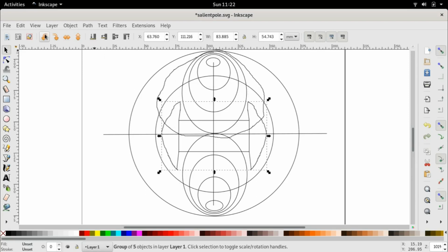In comparison, if this rotor were to be rotated by 90 degrees, we see that it's totally different. Now in this case, since the rotor position is in the horizontal direction, the flux produced by the stator will be much stronger, for the simple reason that now the air gap, or rather the path for which this stator flux can flow, is much smaller. Because now, for example, the flux produced by the stator can flow in this direction in a much more uninhibited manner. So therefore, the rotor position angle does decide how strong the stator flux is.